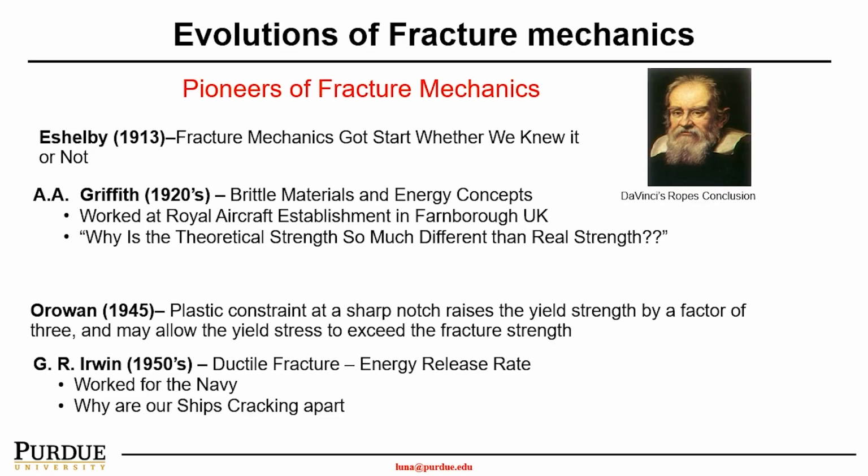Many US ships were cracking apart during World War II due to the poor quality of the build and the low temperature, which caused the ductile material to transition into brittle. So he further developed the Griffith theory and expanded that into ductile fracture, using the energy release rate concept, which we'll discuss in this lecture.